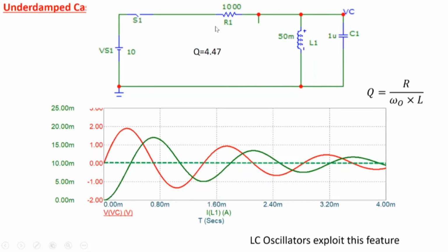Okay, so these RLC series and parallel circuits are very, very important. In fact, antennas, which are necessary for communication, can all be thought of as a parallel or a series resonance circuit here, or some combination of that. So in their equivalent form, these LCR circuits are essential components of all antennas.